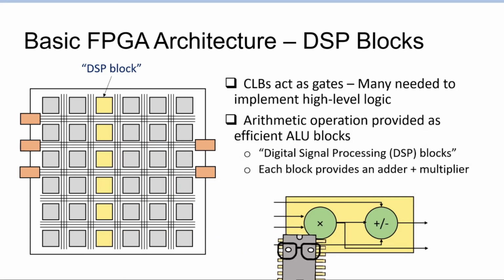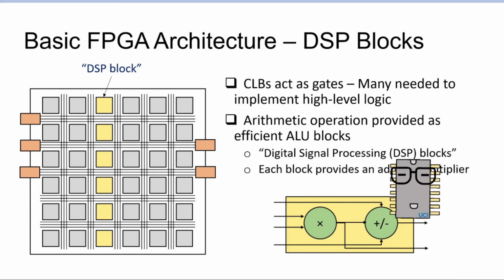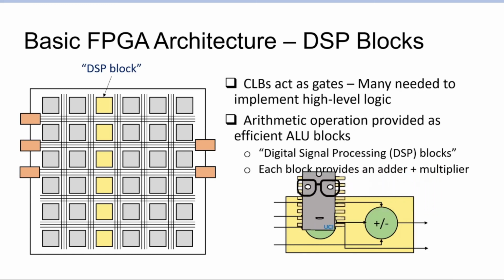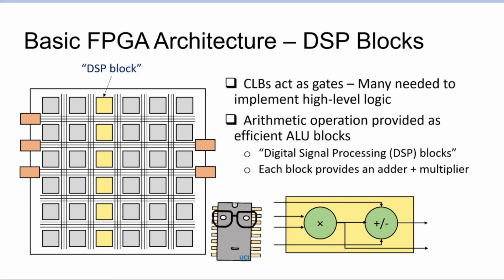These implement a very, very simple slice of the ALU, and you have to build some management logic around this to actually build a functional ALU. All this thing has is pretty much just a multiplier and an addition core. And it is the surrounding CLBs' job to make it actually act like an ALU.